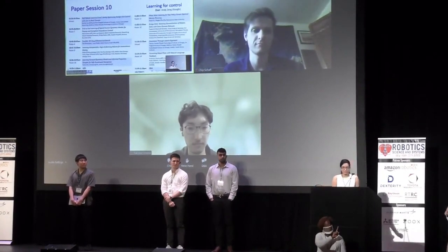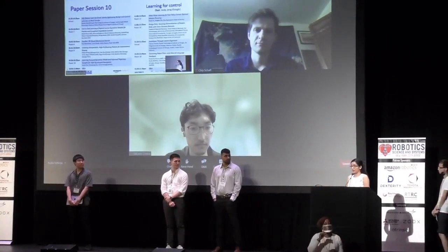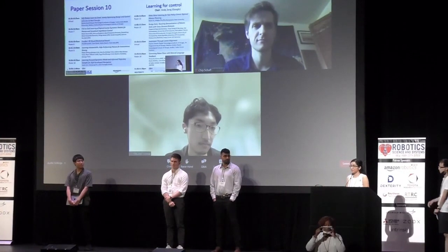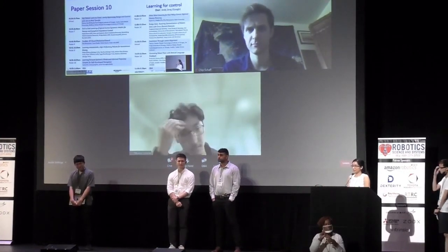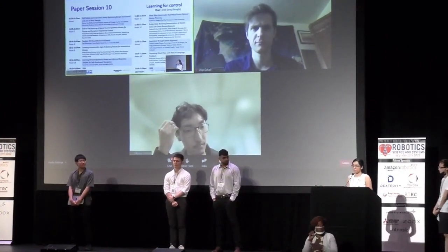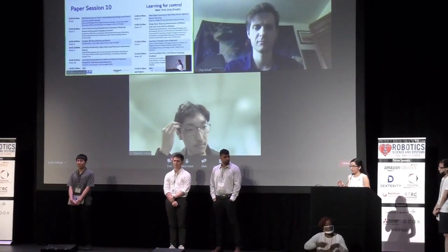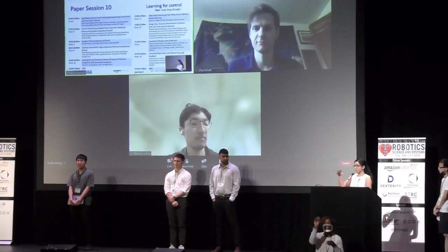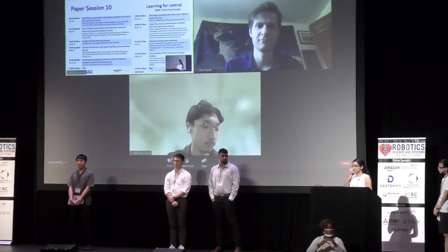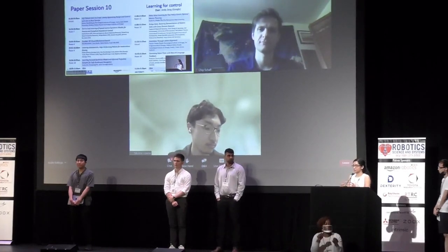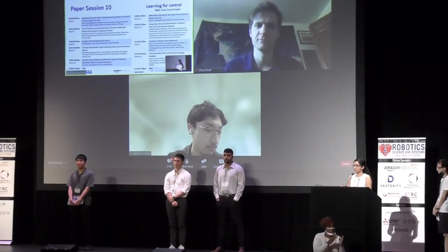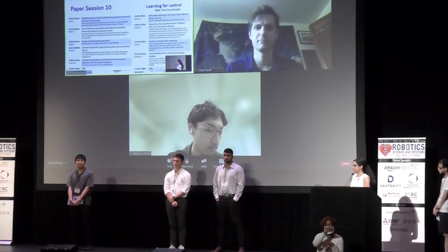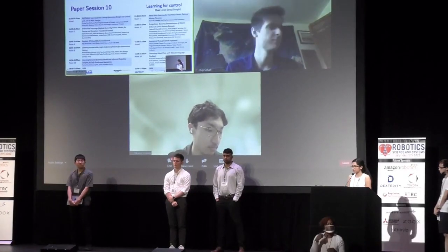So that is actually being considered in the mask scoring. The score of the mask is also dependent on the height of the object on the pile. Normally we prefer to remove something on top of the pile because then the possibility of something being visible to the robot after we remove it increases. So that's considered in the mask score. Thanks.